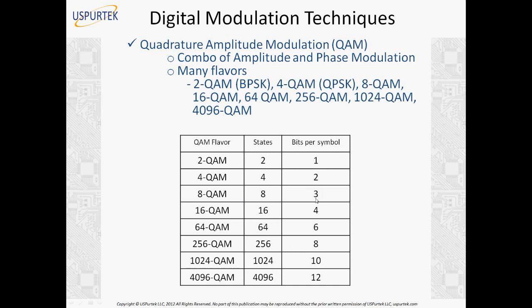Typically, as an example, LTE and wireless LAN very commonly use 64QAM. That means in just one symbol you have 6 bits, and you have 64 states. 2 exponent 6 is 64. You could go even higher, but as you go higher in the number of states, modulation and demodulation become more challenging. Because you have so many states, you need more and more powerful electronics, sensitivity, DSP processors and new algorithms to be able to differentiate each state as the number of states increases.